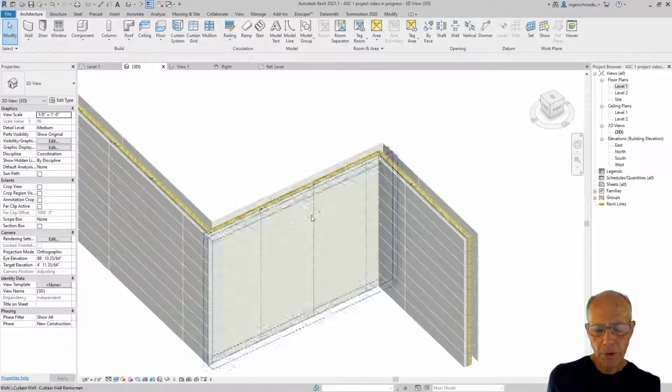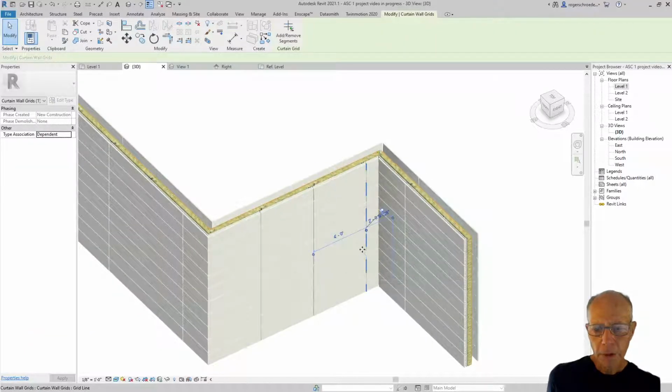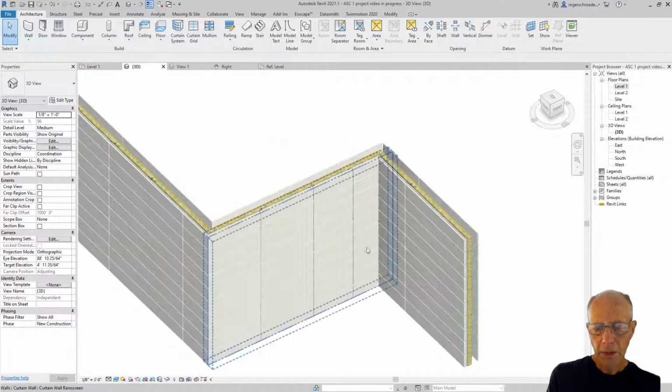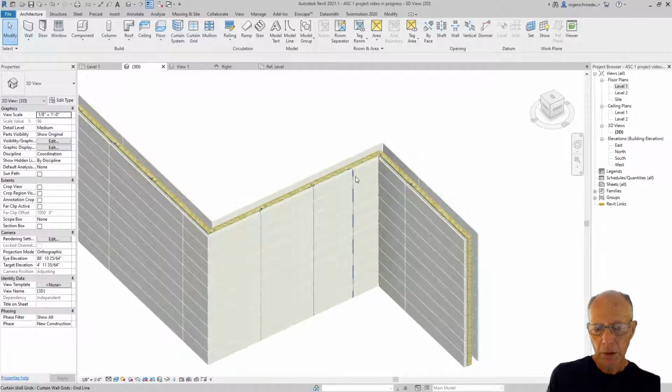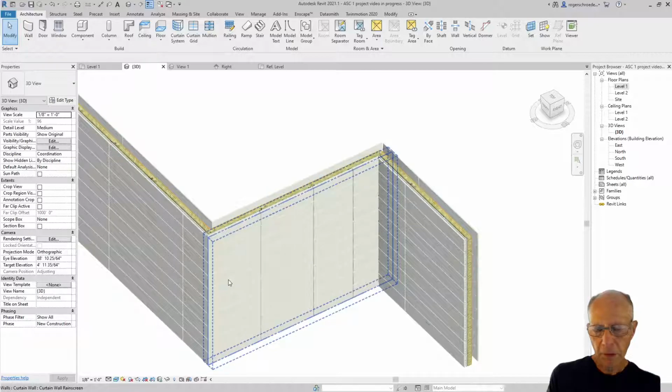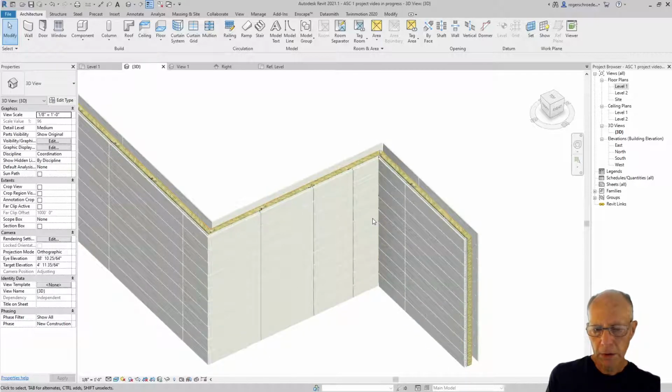This is a time for the kind of issues of design detailing of a curtain wall system. You can adjust these mullions. Obviously, if I didn't like that shorter thing and I wanted to make this panel smaller, I could come in here and adjust that mullion line if I unpin it. And so we have all kinds of flexibility now to control this grid line to make sure all of our panels are equal in length and create a nice pleasant appearance to our panelized system.